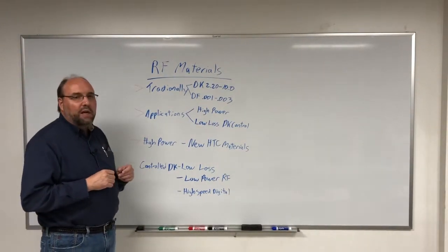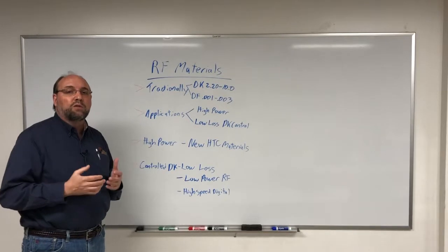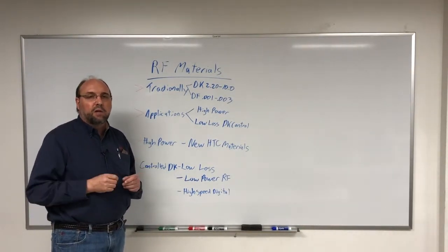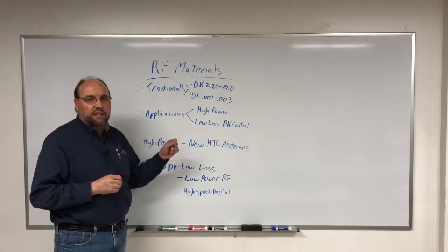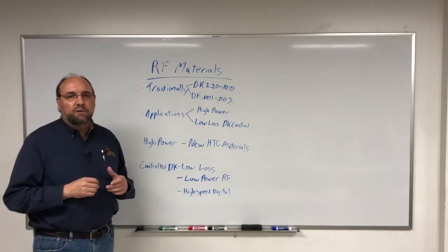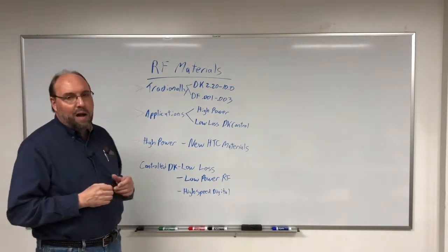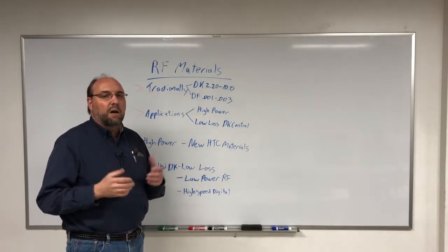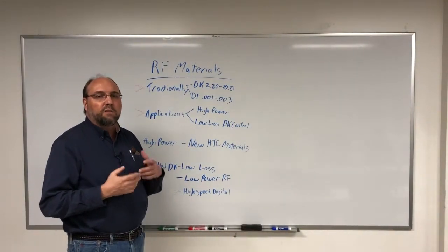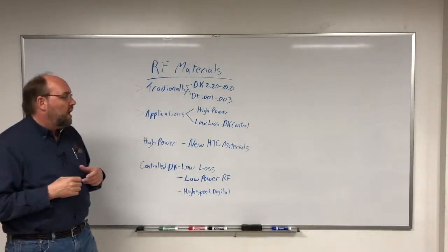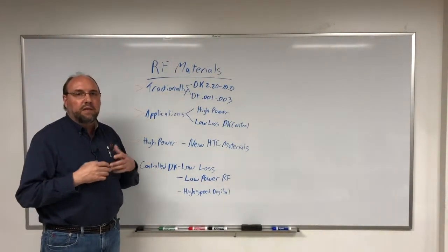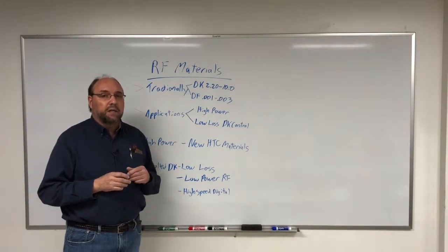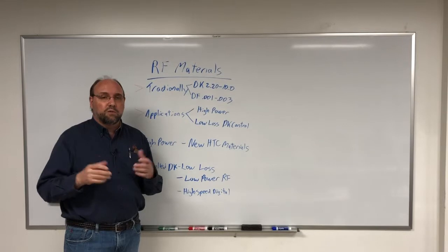With the high power applications, there's been an advent of more ceramic filled materials, or materials with a focus specifically on thermal conductivity, and those are generally called either TC or HTC materials, and those are finding their ways into a lot of the high power applications. The temperature of the circuitry and the temperature of the devices have become of increasing importance relative to how that circuit functions, as well as the loss of the signal along that conductor. In those cases, they've actually wanted to dissipate heat along the conductor itself as opposed to just under the device,